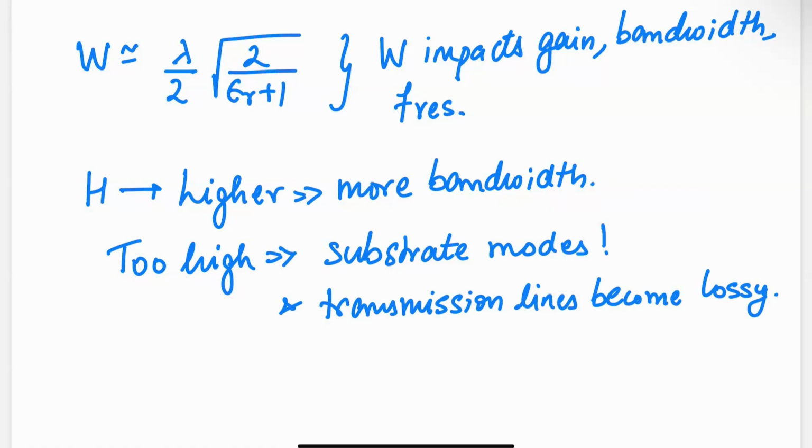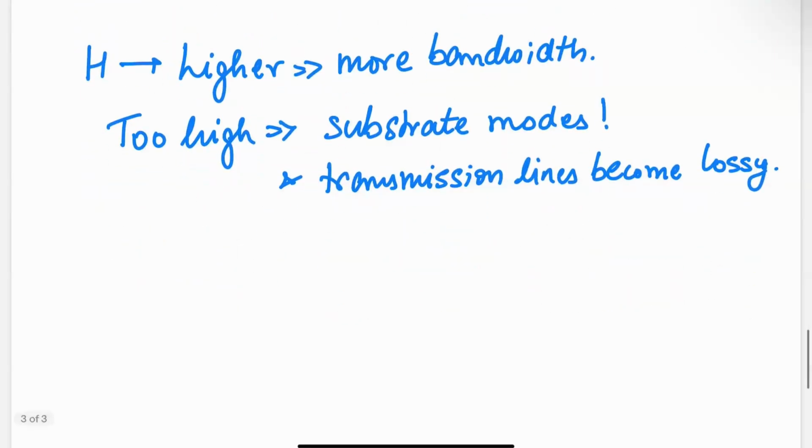Okay, and we'll see you'll have a microstrip line that feeds the patch. And if you make the thickness too large, then the fields under the microstrip line are not confined and then it becomes a radiative line, which you don't want. Right, so there are some compromises in terms of height as well.